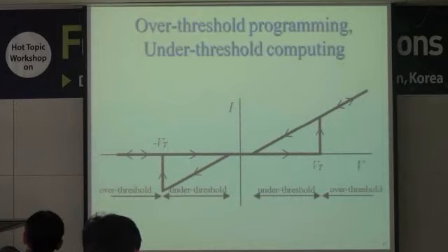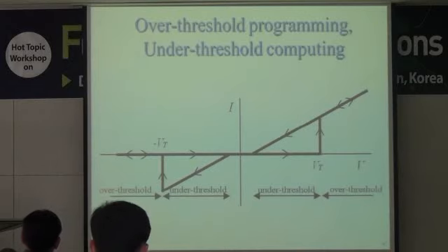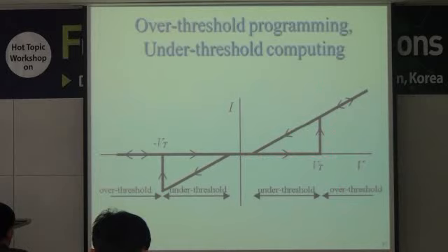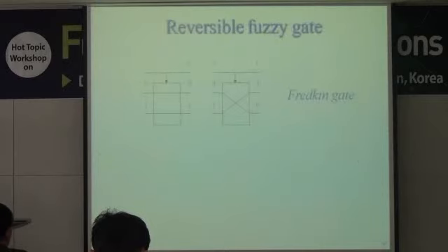Another nice property is similar: if we set the memristors to some values, and then use inputs with a voltage lower than some threshold, the memristor cannot be changed. The set state of the memristor will be kept the same, and this may be used for reversible computing.